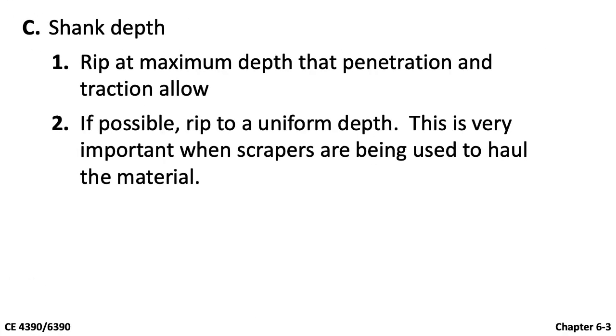Shank depth is the maximum depth that the shank penetrates into the rock surface. This is dependent upon the characteristics of the rock and the machine. If possible, you should rip to a uniform depth. This is very important when scrapers are being used to haul the material. When the rip depth is uniform, you can minimize idle time for scrapers.